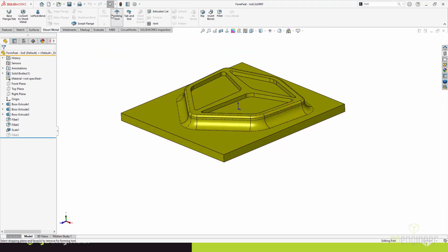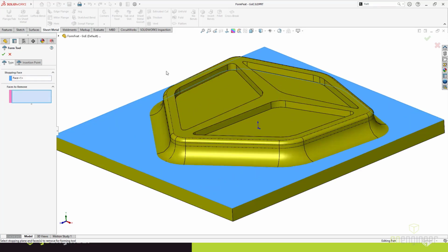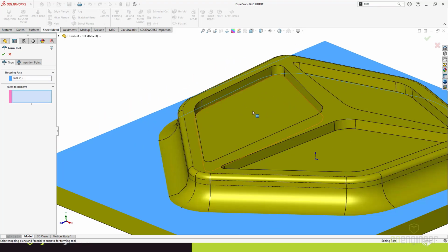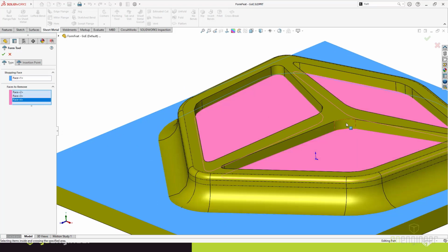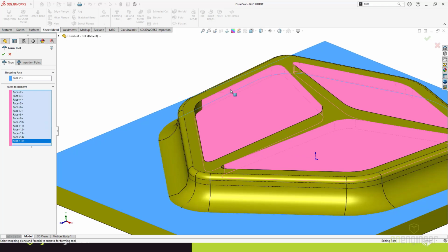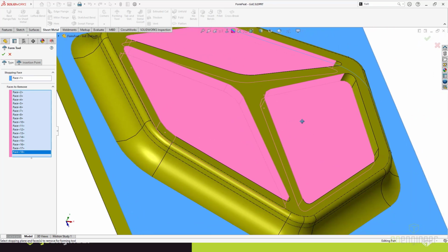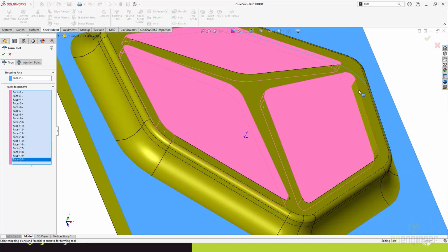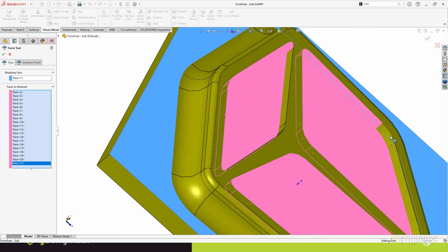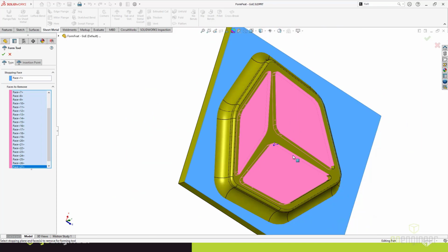So when you do go ahead and run through that basic process here, I'm going to take a little longer on this one because I want you to see what this looks like. But I'm going to use a removal feature here where I actually select a series of faces. Now because of the geometry that I've created here, my right click select tangency doesn't seem to be there. So if anybody's asking in your head why Darin isn't doing that, it's because it doesn't happen to be there. But based on this, it's really worth the work that I'm about to do, because essentially all these faces that I'm selecting on the inside are going to be the stuff that gets ignored or removed.